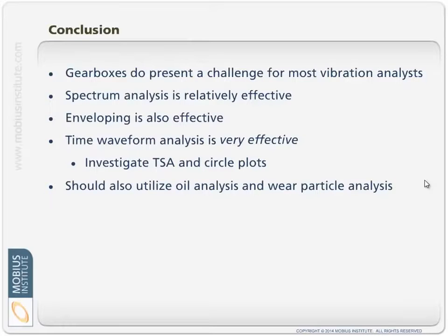A few quick factors. You do have to think about gearboxes very carefully to make sure that where you place your sensors, you're capturing the frequencies of interest, there's a good mechanical transmission path to that point, and that your measurements are being set up correctly. Spectra are useful. Enveloping and the various techniques are useful. Time waveform analysis is very important. Have a look at time synchronous averaging, have a look at circle plots if your software has it.